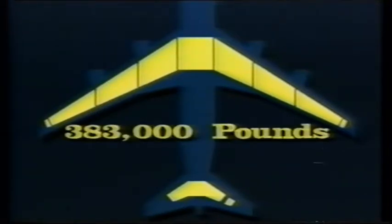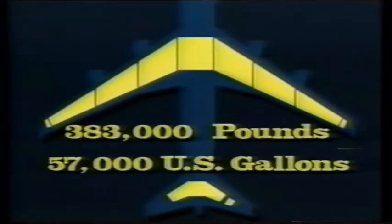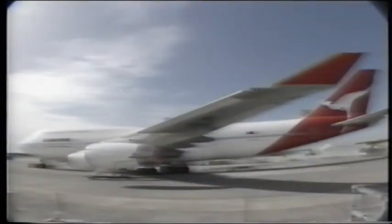Fuel is also stored in the center wing tank and in the optional horizontal stabilizer tank, or HST, and surge tank. The total fuel capacity is more than 383,000 pounds, or 57,000 U.S. gallons. Many of the fuel system components are located in the tanks. Access to these components is through one of the 28 panels in each wing.